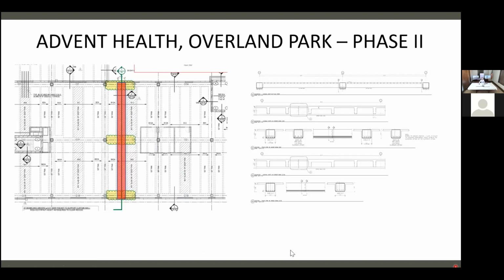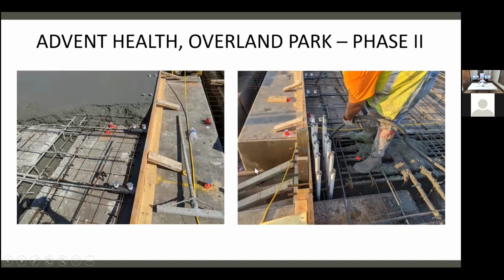So this hospital we did down in Kansas City, 6-story, one-way reinforced concrete joist system. They were 2 months behind schedule. They're at a 5th span over here. So they required back shoring on this long span, column, long span on the right. These are our shop drawings on the right-hand side. And this is the first pour installation.